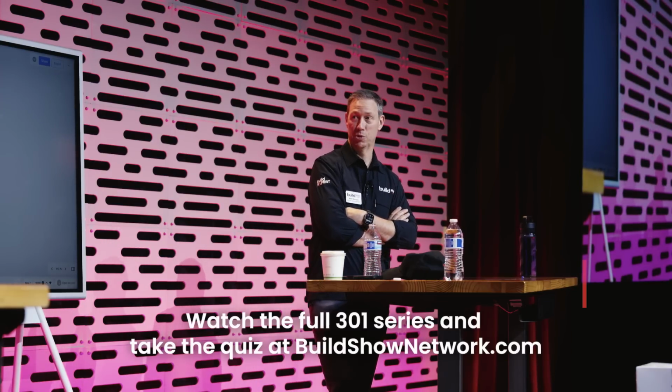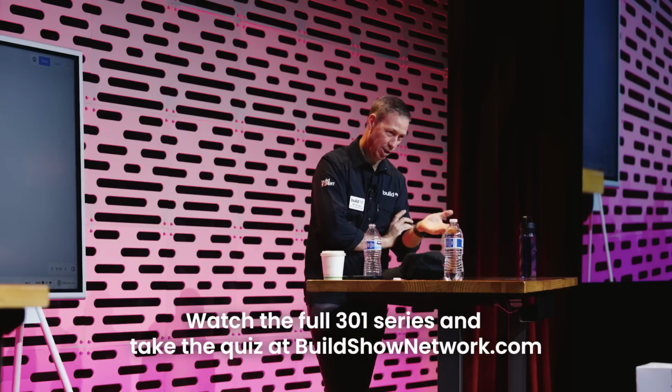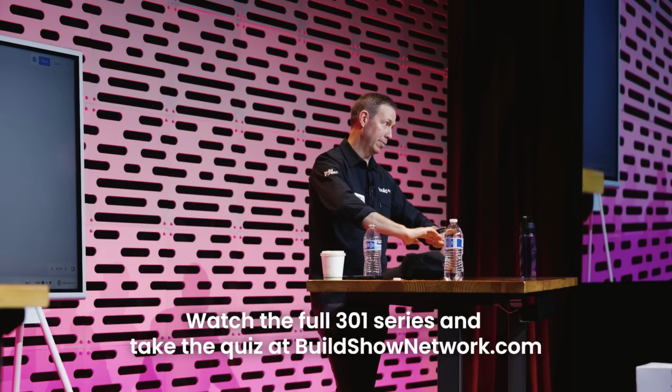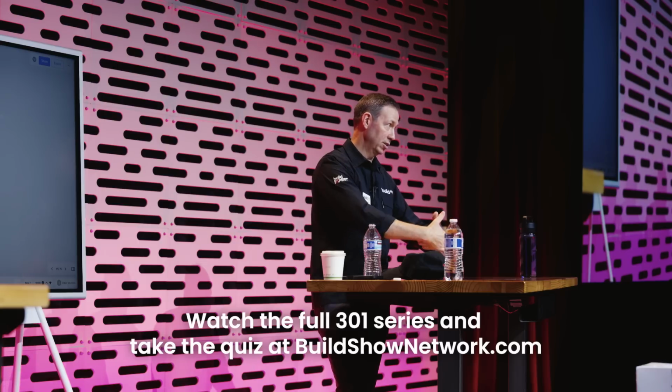I first saw that detail on a Wade Paquin job years ago. Had never seen it before. It looks like a bathtub sprayed in there. And I'm sure it's obvious, but just to say it anyways, it's going up the wall by 1 foot or 2 so that when the slab gets poured, it's making a thermal break at the edge of the slab.